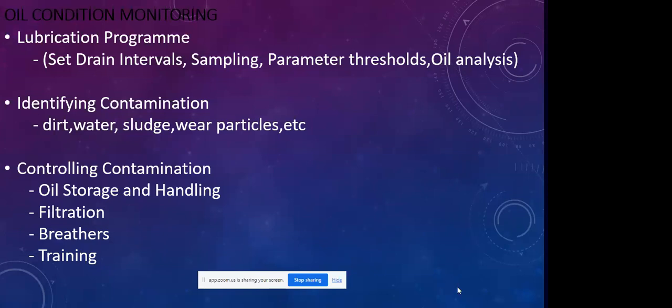This air condenses and turns into water. And when you have water, even as small as 5 or 3 ppm, going into the drum, then it's likely to react with some of the additives in the oil, degrading the additive and contaminating it even way ahead of time. And what contamination does is that it reduces the drain interval of this oil. And reduction in drain interval also means cost.